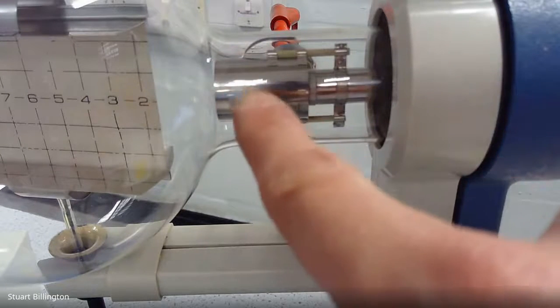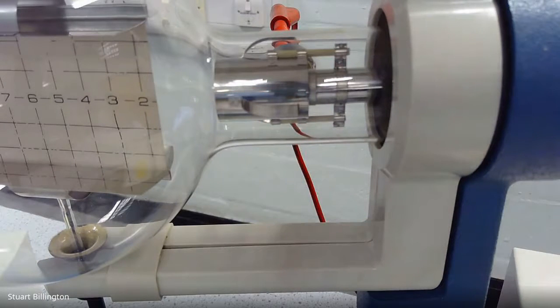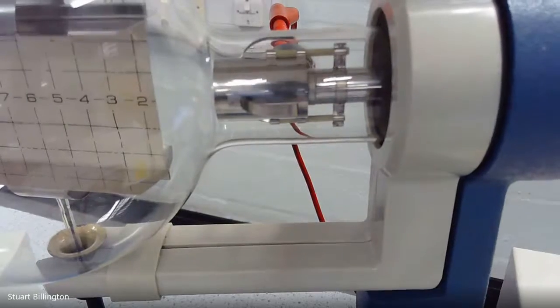And then just next to it, we've got this very large cylinder. And again, that's going to play the role of the positive plate. In fact, if you look in, I don't know if the camera is going to be able to see inside, it is actually a vertical plate inside that cylinder. Can you just see that there's a vertical surface just inside that cylinder, and it's got that horizontal line across it. That's the gap in the plate. That's what the electrons are going to come flying out of. And rather than being a dot, it's going to be a fan-shaped beam that flies out, a horizontal flat beam of electrons.